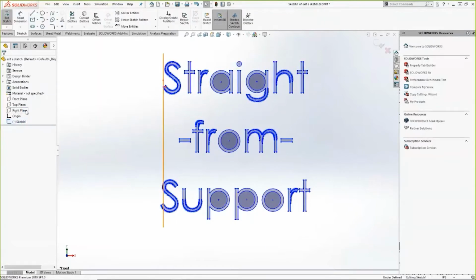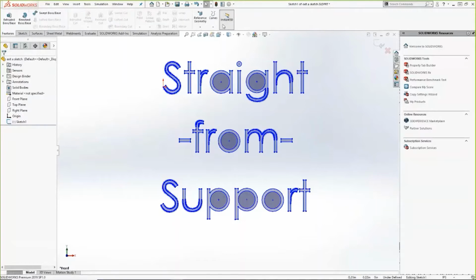Now I see this in tech support. We could see this in 2 different ways. One, why am I accidentally exiting my sketch? I've heard a lot of people run into this, especially when teaching essentials. People will be drawing, and then they'll accidentally double click and it will pull them out of the sketch. Why do I keep accidentally getting exited out of the sketch? Well, it's because Instant 3D is probably turned on, and that's causing you to exit the sketch there.